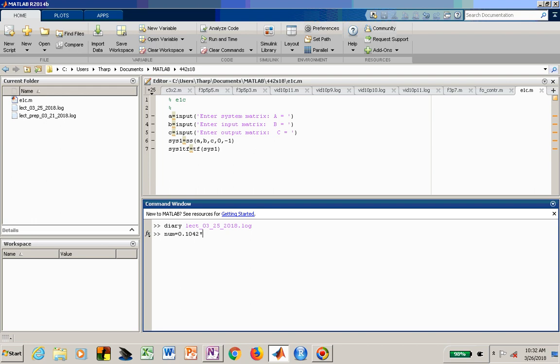The gain, K, was 0.1042, and we're going to use that to scale the polynomial z, which in MATLAB corresponds to the vector [1 0]. There's our numerator polynomial. Our denominator polynomial is z squared, and then we have minus 2 times the real component,